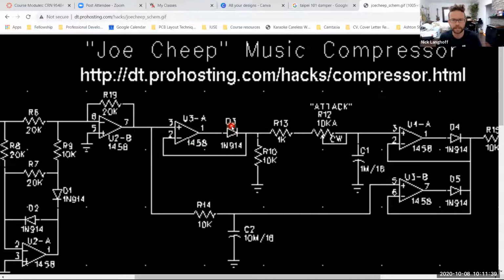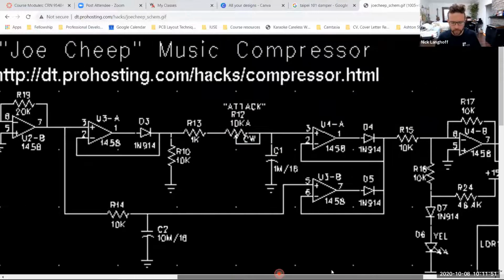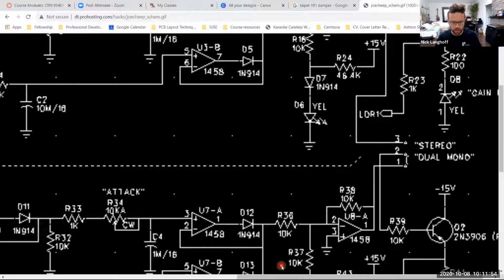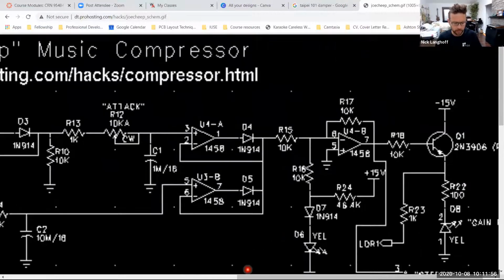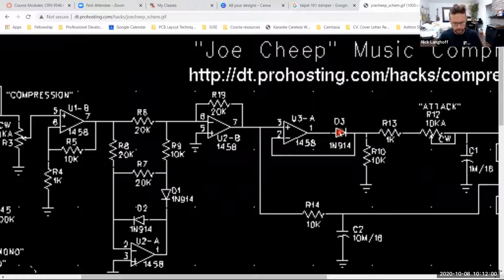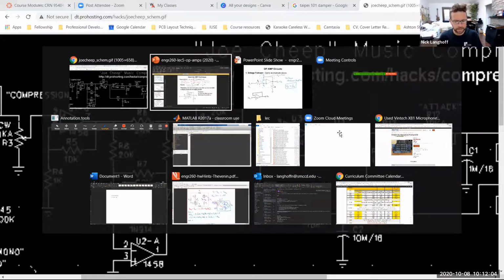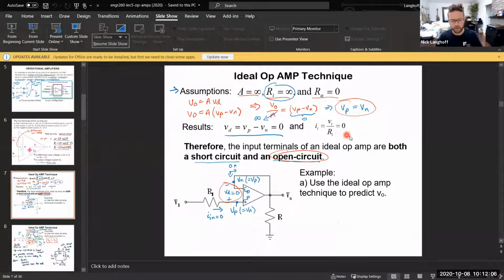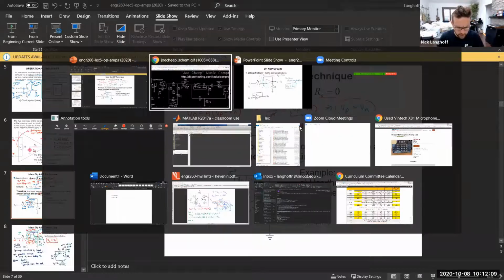It's almost connected directly, except there's a diode in the path. That is almost a buffer. It's actually a rectifying buffer, but the reason I pull this up is so that you can start to see common op amp blocks. When you stick a diode in there, that does do another action. It's a rectifying follower, but we can see circuits where you'll start to see those in examples there.